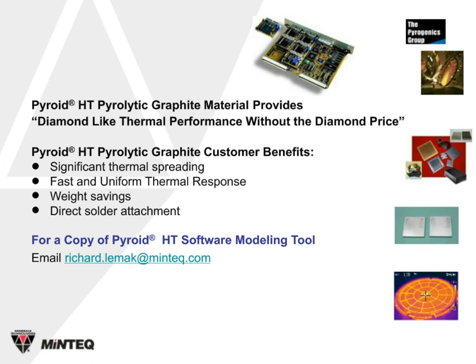And to give you a summary of what we've discussed this morning before we go to the Q&A, we've introduced you or reminded you of an advanced material called Pyroid HT pyrolytic graphite. That material evidences extremely good thermal spreading due to its 1700 watts per meter K thermal conductivity. We've seen evidence of a fast and uniform thermal response. It has weight savings, and because it can be metallized, it affords the opportunity for direct solder attachment.